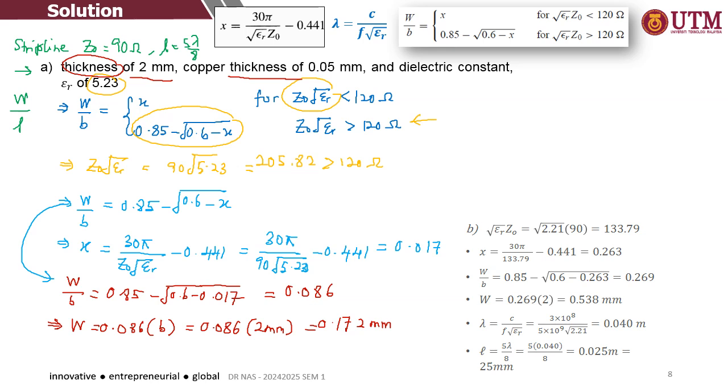Okay, so please be careful with the unit. If you want to use millimeter, use millimeter for all calculation, or else you need to convert it into the standard unit, meter. Right, next you have the W. How about the L? The L is given in the question as 5 lambda over 8, but what will be the actual value? So what is your lambda? Lambda equals C over F. C is the speed of light divided by your F, given just now as 5 gigahertz.